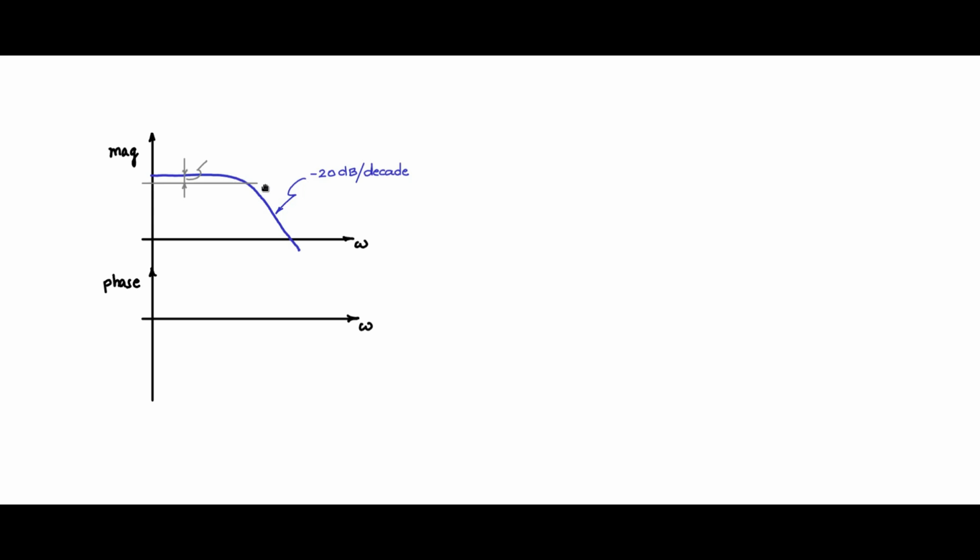So this is the 3 dB below point. Now at this point the gain is 0.707 with respect to the flat portion. Now take this vertical line which cuts the frequency and look at the phase curve. The phase at that 3 dB point will be 45 degrees. So this goes from 0 degree to minus 45 degree, and eventually this phase curve will reach 90 degree.